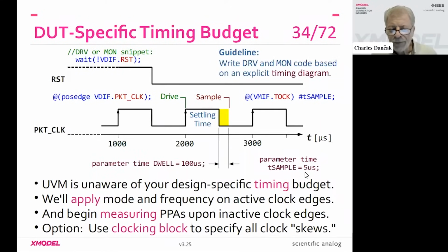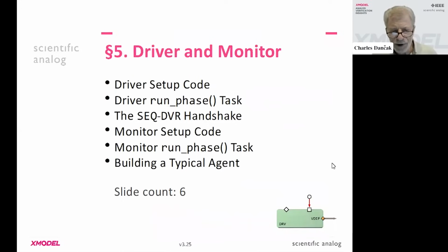As a guideline, and believe me, many of these guidelines came out of hard-learned lessons: be sure you write a timing diagram and get it all settled before you start coding the driver and monitor. You'll save yourself a lot of effort. Hard experience. Okay, let's go on to the driver and monitor details in section 5.